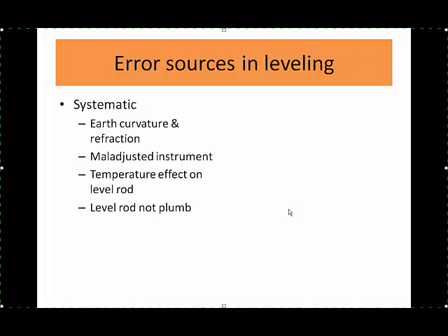When you are dealing with a horizontal line of sight and a vertical rod, then you will get the minimum reading between the point measured and your line of sight. But if the rod is not plumb, then your reading will increase. This type of error is a systematic error only if you know the slope of the rod. If you don't know the slope of the rod, this is merely a random error.